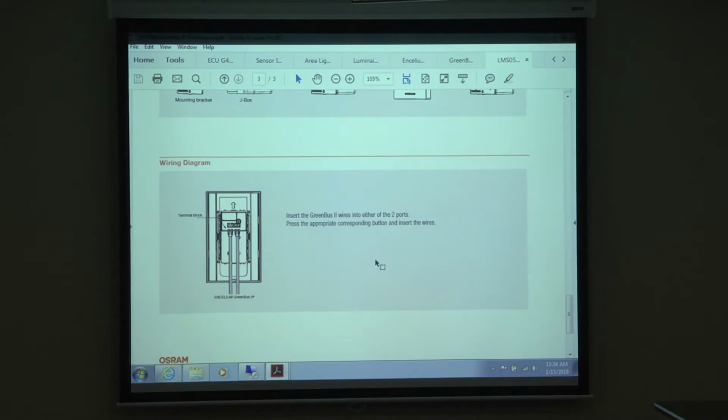However, in actuality, when you're on site, you cannot necessarily do that. On site, the guys on the computers are just seeing point from here to here to here, right? But in the field, there may be ductwork in the way. You can't go there, you have to go around somewhere else, and by going somewhere else, you hit something else, right? So the new design that we have is called a zonal design, in which we give you an area, like say 5-6 rooms with devices everywhere. So just run your cables as you see fit, right? You can go from here to here, or from here back here.